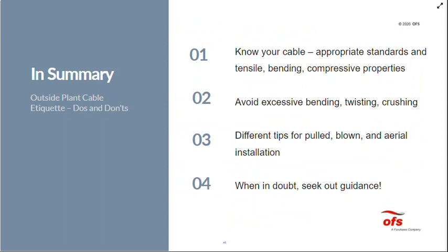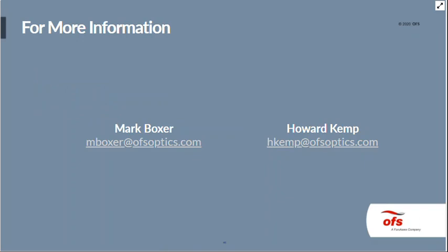So in summary, know your cable, the appropriate standards, and the tensile, bending, and compressive properties. First of all, that's the most important thing. Once you know what you're working with and what it can do, then just make sure you avoid excessive bending, twisting, crushing, and tension. It's not a hard thing. Howard provided a number of different tips for pulled, blown, and aerial cables, and overall, when in doubt, absolutely seek out guidance.